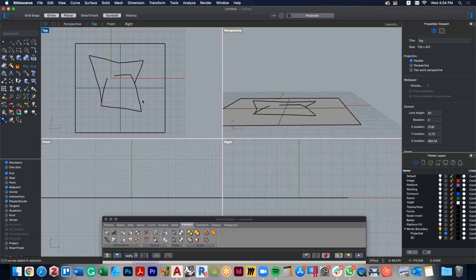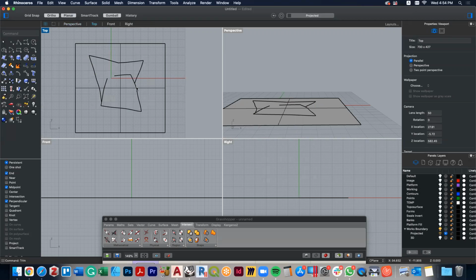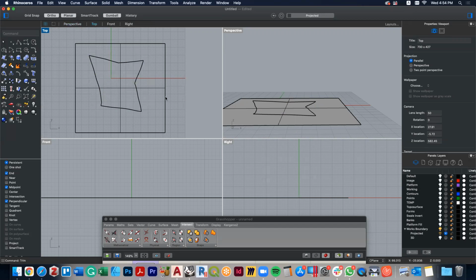So now what I'm doing is I'm actually going to trim it because it's all flat now. Because it's all coplanar, which is a key term. Everything's easy when it's coplanar. When things are lying together, coplanar is easier. So if I go to trim now, I can trim that off there like that. And so that's now the overall extent of the works.